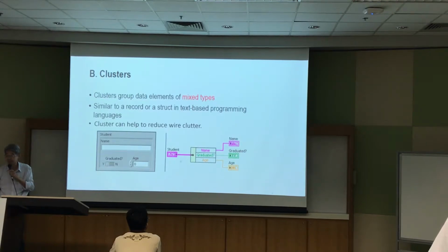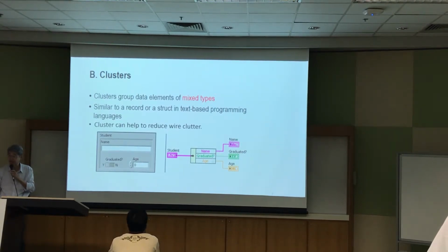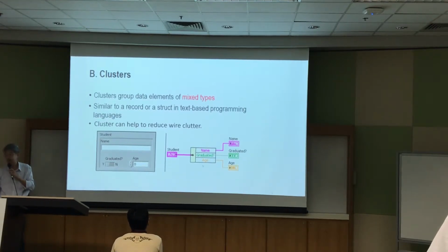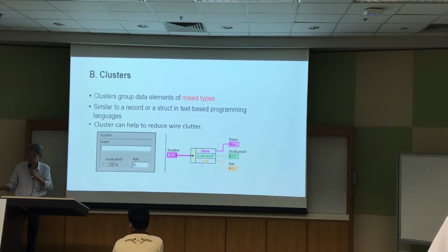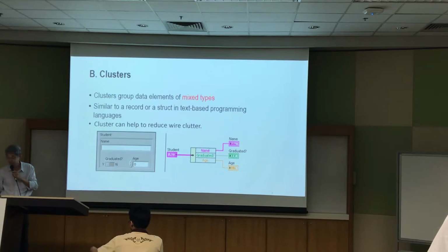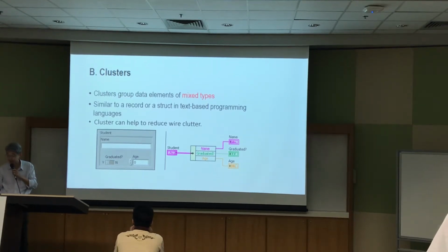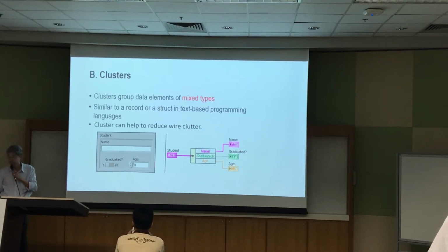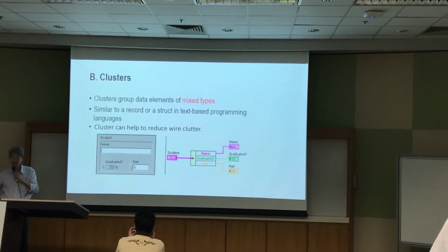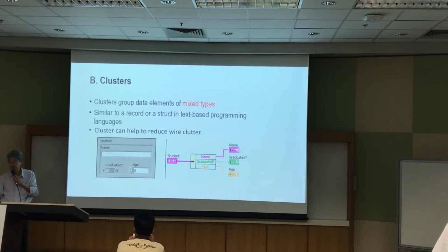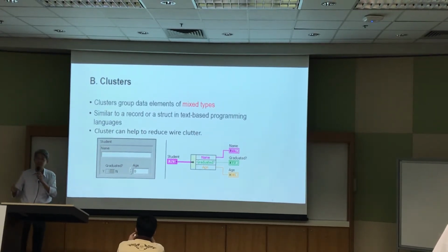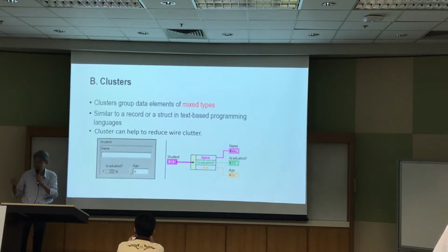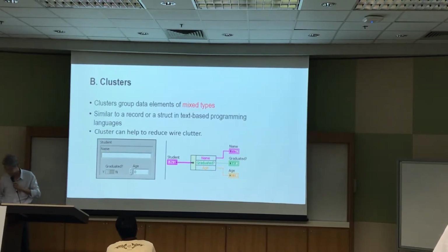You unbundle that bundle into separate items in that cluster. So one to many is an unbundle function, very obvious. And this one is unbundle by name. You can see all the different names of the items are shown here. If you just use unbundle without by name, then you don't see these labels listed. Not so obvious. I prefer to use by name all the time. Okay?